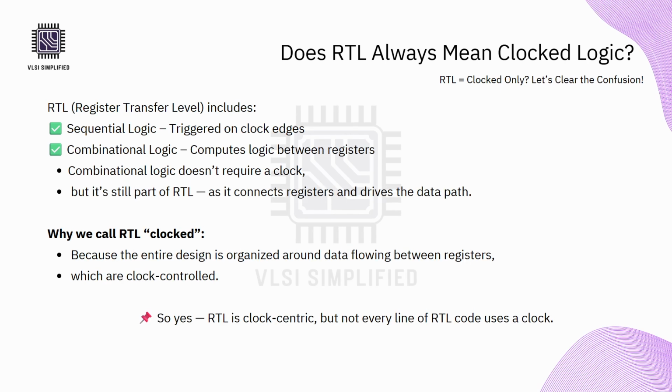Alright, before we go further, let's address a common and important question. Does RTL always mean everything is clocked? The short answer is no, not everything is clocked. In fact, combinational logic is a crucial part of RTL design. It is used to process inputs and drive outputs between clocked registers.